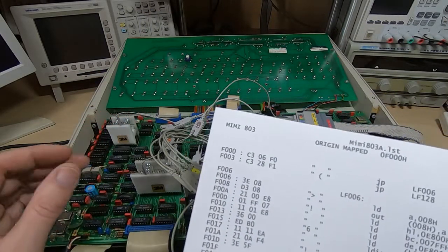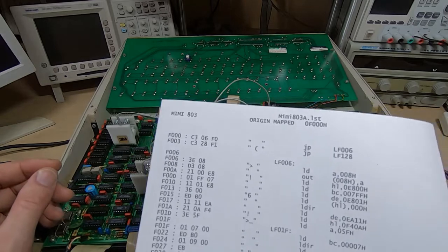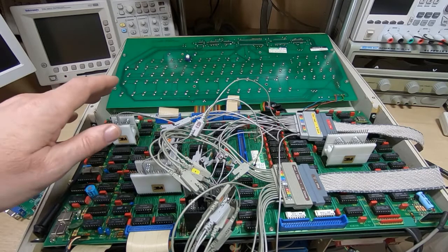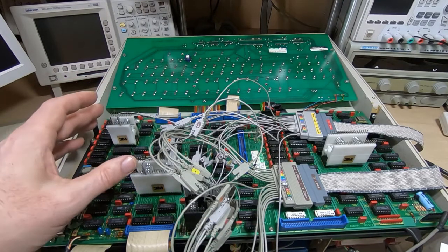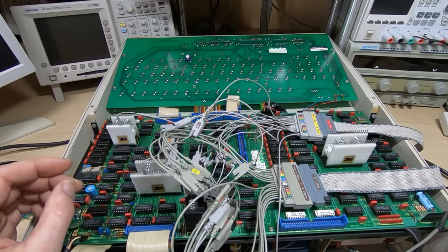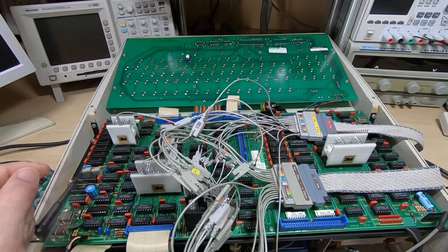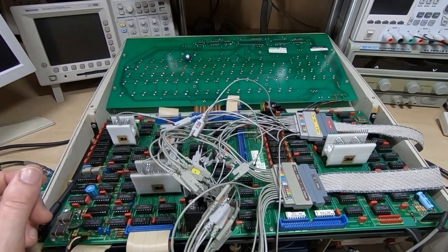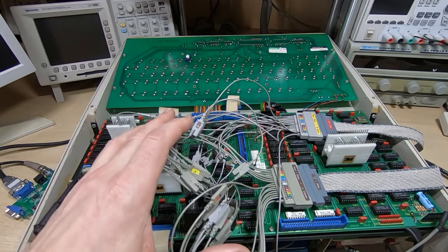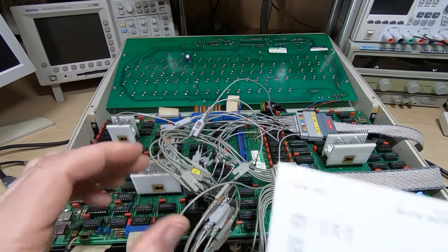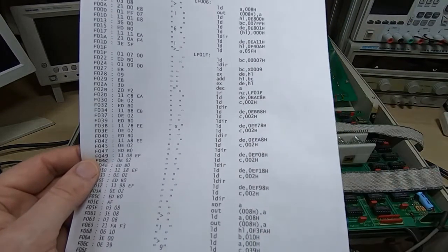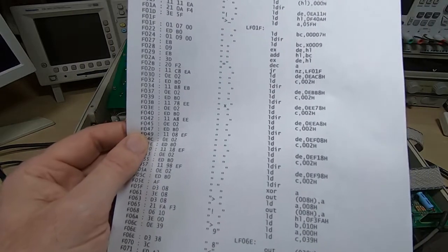I'm not going to go through how it functions on this particular machine in this case. It's not important for the fault finding we're doing here. The only thing to bear in mind is that if you are trying to trace through this with the scope, you might find that the address lines aren't connected exactly as you might expect them to be. Also, this is probably a banked system as well, so there will be other complications involved. But for our fault finding task here, we don't need to get involved with that. All we need to be able to do is go through the code and be able to trace through and follow it through from address to address.